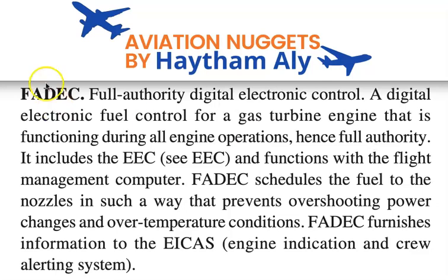FADEC protects the engine against overspeed and over temperature. During engine start, the FADEC may abort the starting sequence or may restart it.